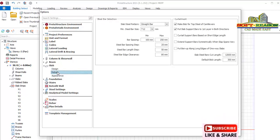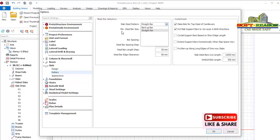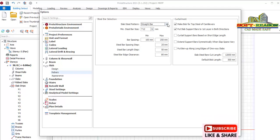I'll go back to the rebar. So in these provisions, we are considering a rebar size of T12. All right, T12. The steel pattern is going to be straight. We are not going to use the bent-up bars pattern. It depends on the one that is normally used in your region. In my region, we use a straight bar.